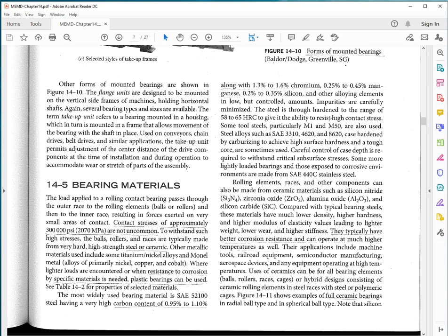Over time, you don't want to have any phase change. Minute changes in dimension can occur with phase changes. Everybody knows of quenching, where we have phase change by rapid cooling, but phase change can occur over extended periods of time,